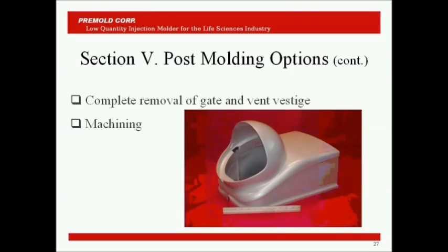This part could be molded as one piece with the rim process because it is forgiving of those varying wall thicknesses. So consequently, the part cost and the tooling cost were less molding it as one piece in the rim process. Also eliminated the joint that would have run down a very cosmetic area of the part, and it made the part stiffer and more structural, molding it as one piece instead of two pieces fastened together.